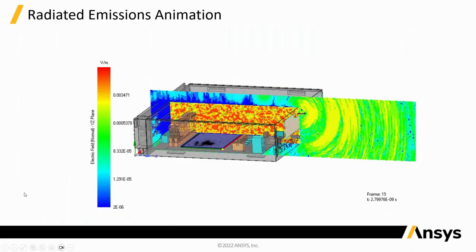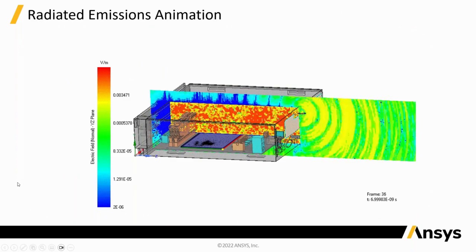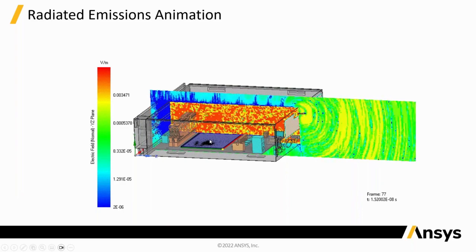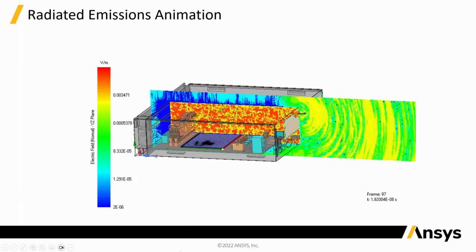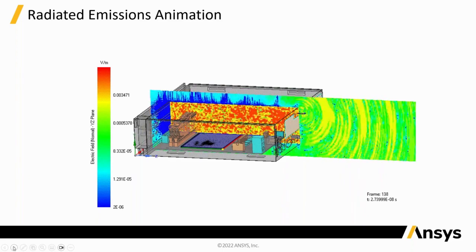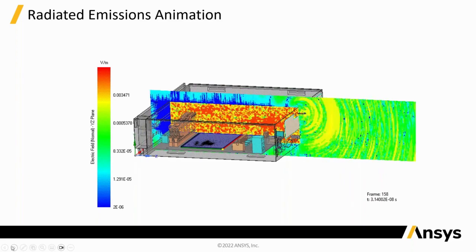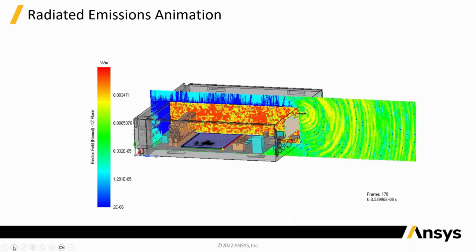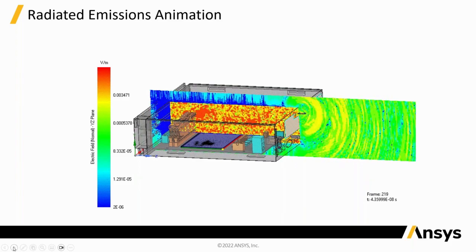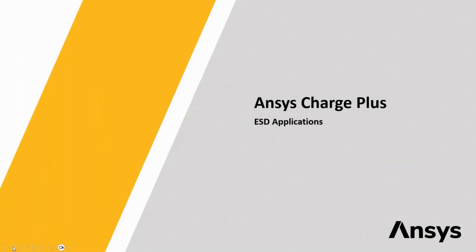And you can just get an idea here. Here's just a view of the radiated emissions, both inside and outside of the box. This printed circuit board, that emission was imported from a result that they had done with the Maxwell tools or the HFSS tools. So we imported a bunch of the components and carried forward with a full system level view, including all the cables and harnesses in this model.